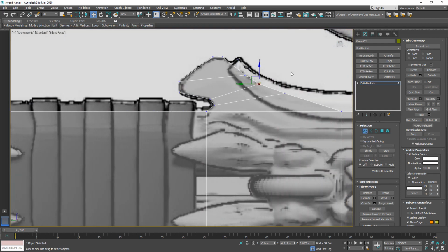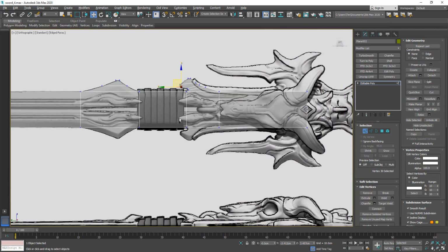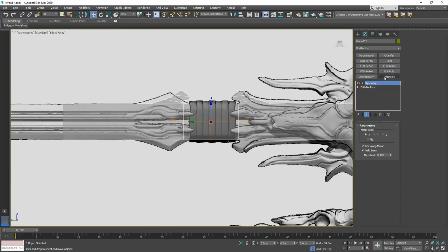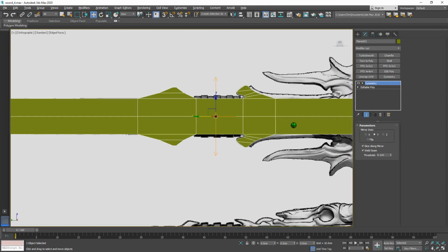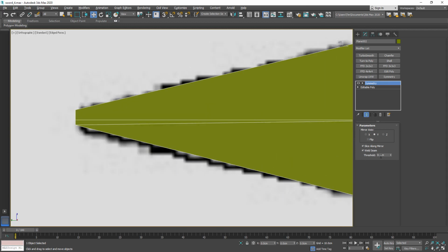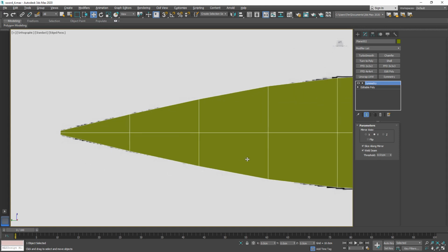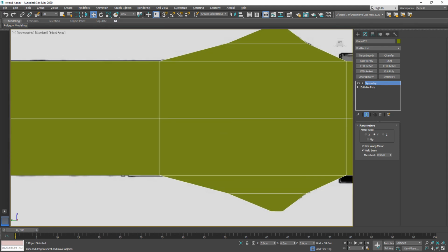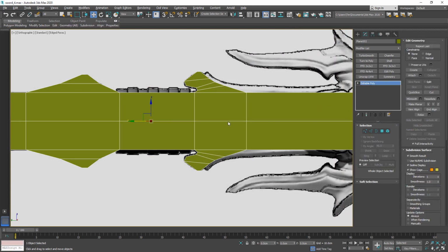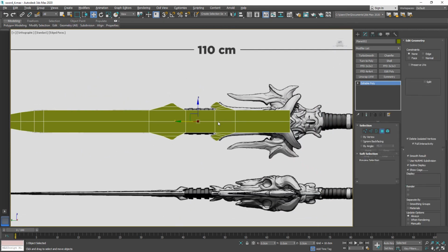On the upper right, let's press left again so that we are aligned here with our reference image. And I'm just gonna drag a bit here on that vertex, position it a bit better. And now let's have symmetry mode on the y-axis so that we actually have that on both sides. If you see some weird stuff like that, you just have to put the threshold a bit smaller. 0.01 usually works great. And now I'm just going to collapse that.